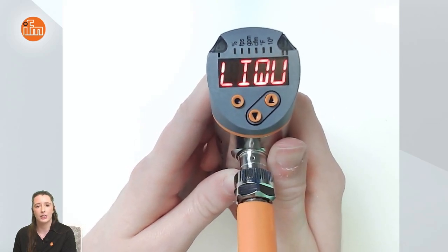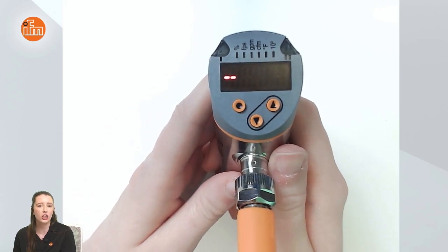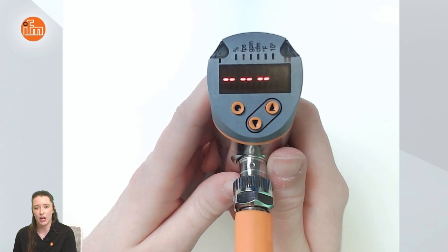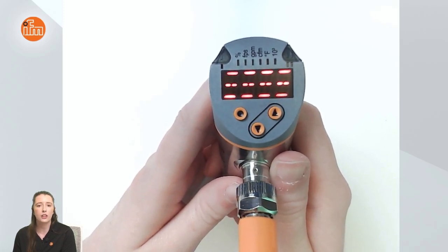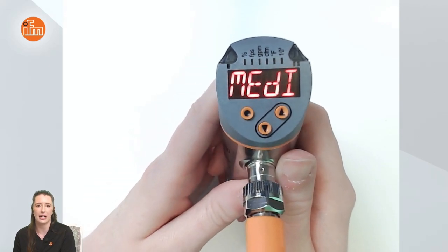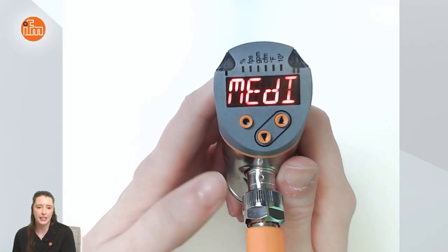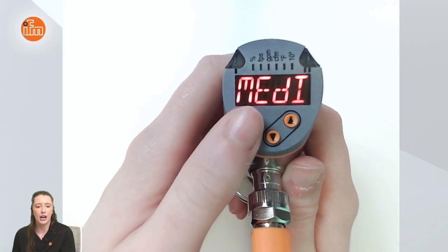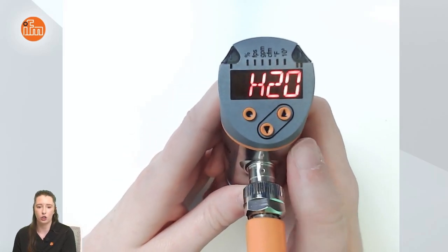When you see your desired parameter setting, you'll press enter. When changing the mode of the SA series flow sensors, you will receive these dashed lines across the display because it is resetting the mode. Once you see the 3 rows of dashed lines, you can press enter to go to your next parameter setting. In absolute mode, which is the liquid or gas settings, you need to set your media type. So when you see MEDI, you'll press enter. You can see it is factory set for H2O.